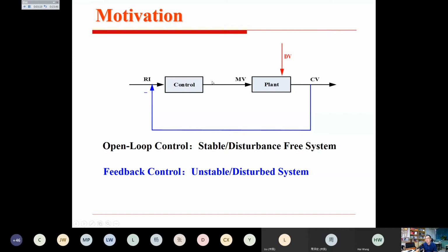So if we use feedback control to reject the disturbance, it's not an in-time control action, because only when the error is large will the control action reject the disturbance, because there's slow dynamics between the disturbance and the output, that's the controlled plant.